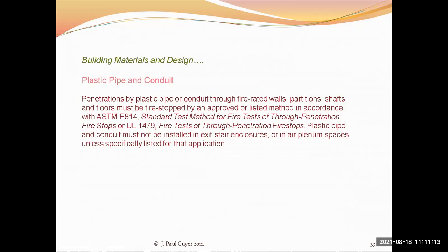Building materials, a point is that, as an example, in a common type of air conditioning system in a building, the supply ducts run to the occupied spaces, discharge air into them. And then the air pressure pushes the air out of the occupied space into the plenum space, which is the space between the floor deck above and the drop-down ceiling. And there is no return duct system, but a plenum, that space above the ceiling is the return duct to return the air back to the air handling fan. And so that is the return duct.